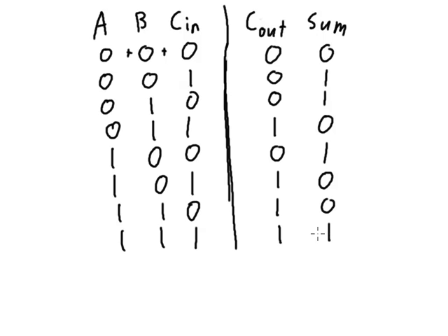So now I've got a new truth table, 3 inputs and 2 different outputs. So we're going to consider the logic expression for the output a little bit differently here, or separately. So we'll figure out the carry out and we'll figure out the sum. So for the C out, we can use our rules for figuring out a sum of products expression from a truth table.